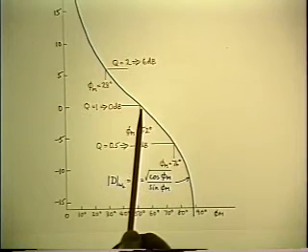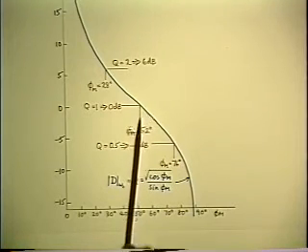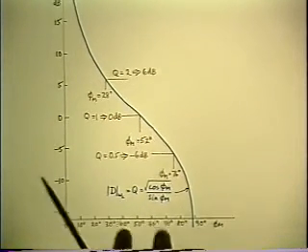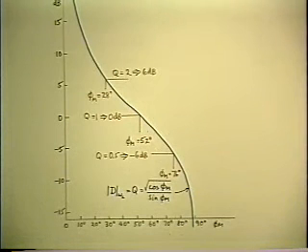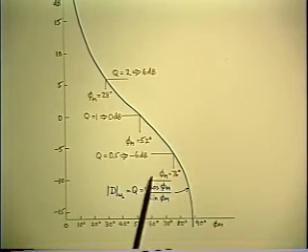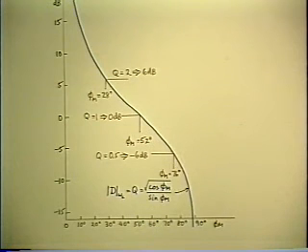Q of 1 requires a phase margin of 52 degrees, and I would tend to translate that into something to remember, that you never want to let your phase margin get less than 52 degrees. Worst case. Not nominal, worst case. Now that may be tough to do. That doesn't do anything to invalidate this. Yeah, it's tough. You've got to live with it.